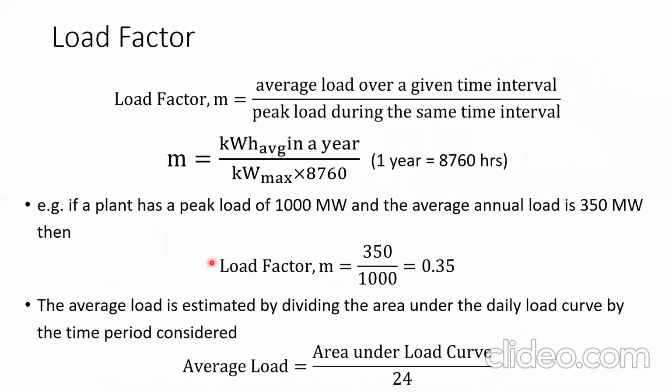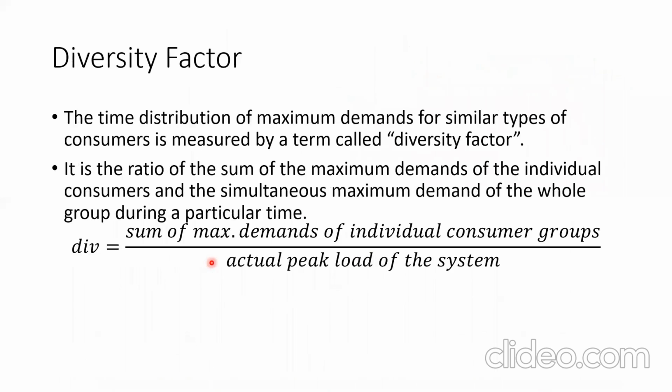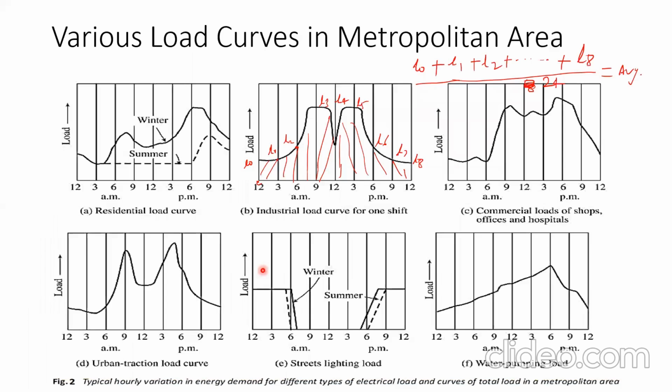You have to add all these maximum demands to form the numerator of this term, and it must be divided by the actual peak load of the system. I mean all the curves, the residential load curve, the industrial load curve,